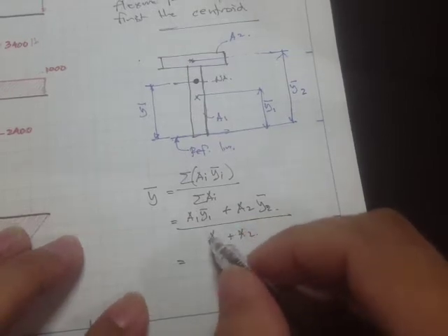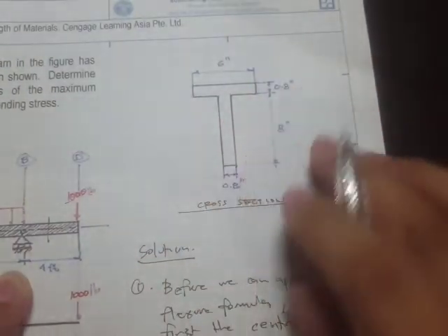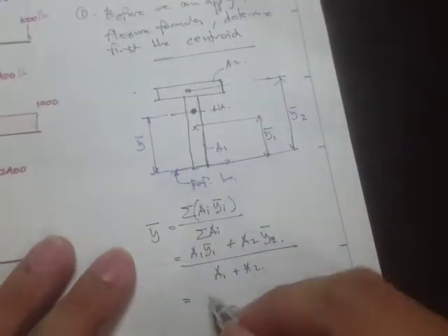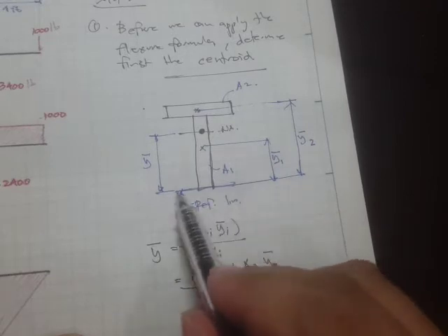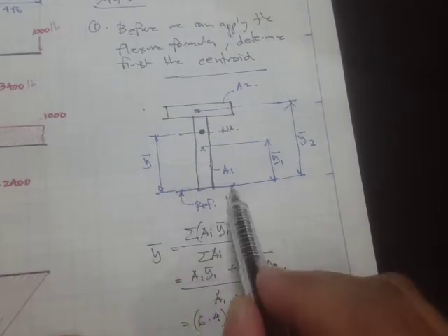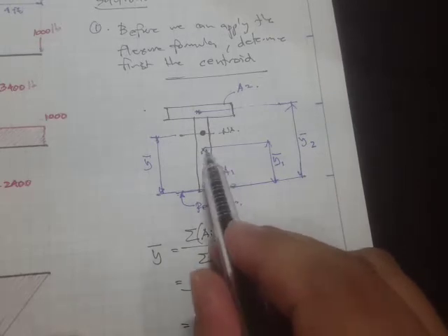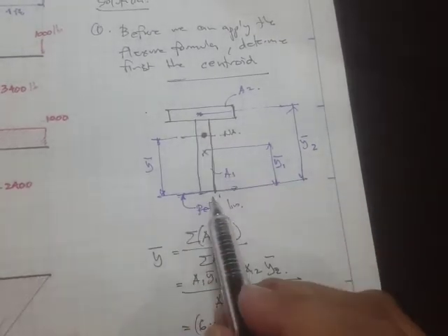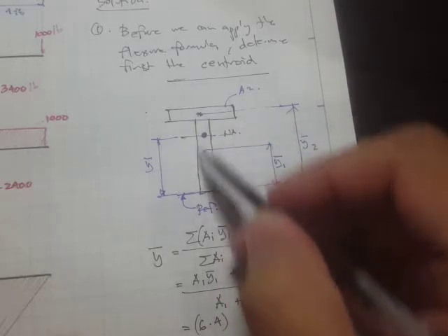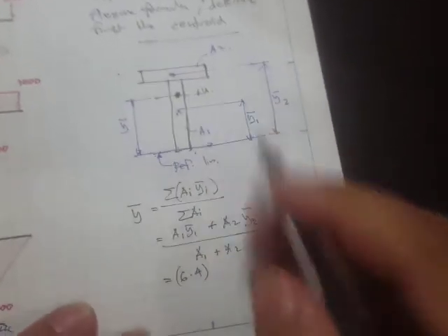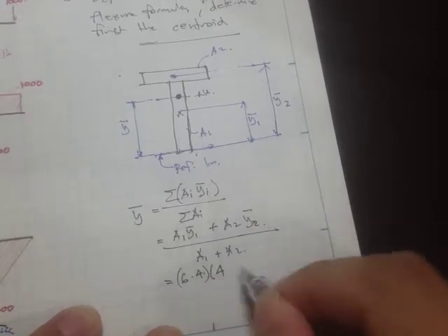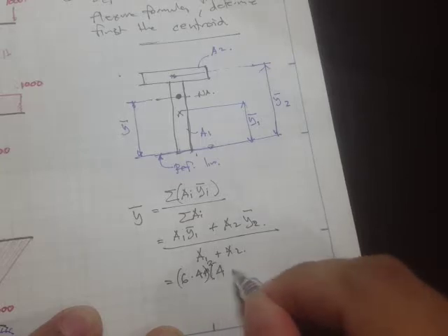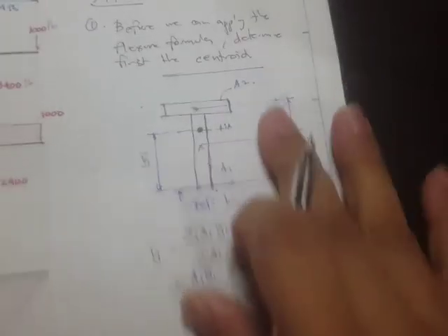the area is, from these dimensions, 8 times 0.8, that's going to be 6.4 times the distance. So from the reference line to the centroid of this first shape, since the total length is 8, then this is just going to be halfway, that's just going to be 4 inches, right? So this one is inch squared, and this one is inch, okay, plus the area of